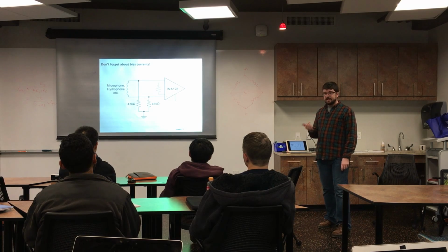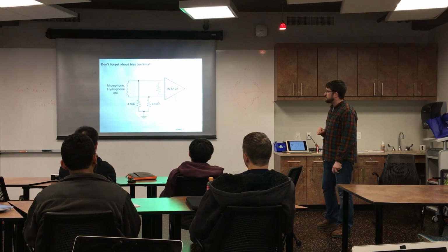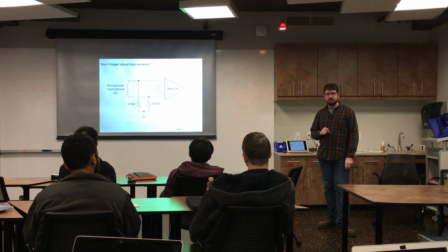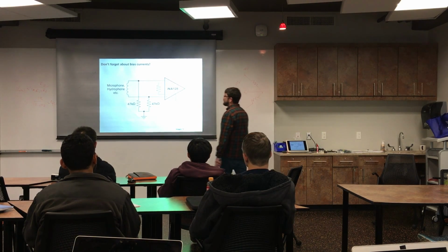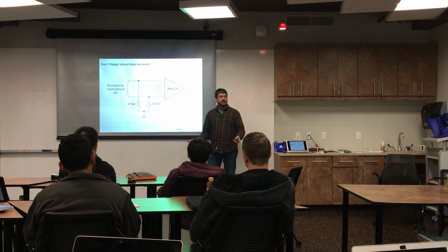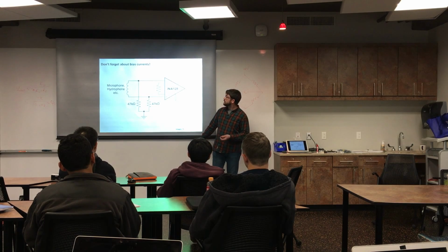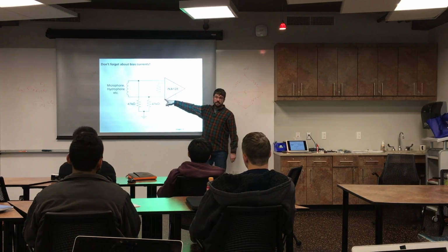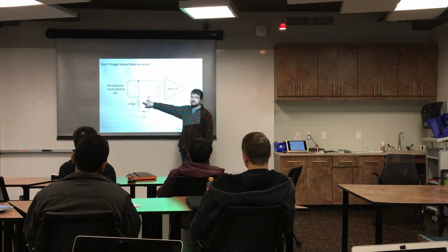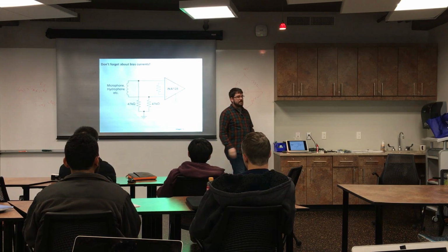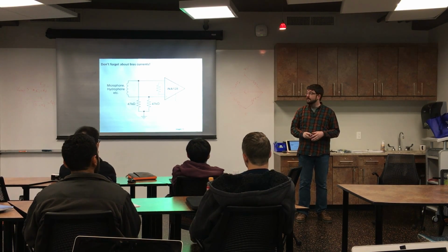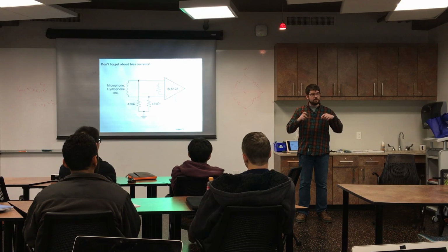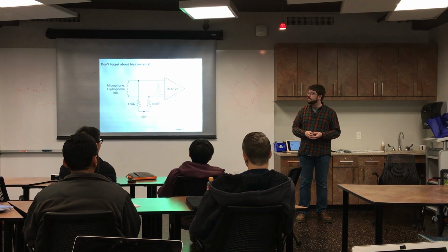They also mention in the datasheet something we talked about last time, which is don't forget about providing a path for your bias currents. So if you've got something like a thermocouple or a microphone that's going to be generating some current, it needs to have somewhere to go. And in theory, no current flows in here. So use a couple of high-value, well-matched resistors and give that bias current a ground path. Otherwise, you will get very erratic behavior. You're not going to have to worry about that for your circuit this week, though.